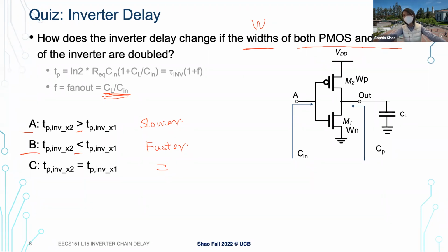But sometimes it actually makes sense to make more transistors or put more gates together that could potentially optimize the delay. But then we step out even more: at a high level, delay and throughput are two different optimization metrics, right? So we talk about the 1 gigahertz race, right? Back then it's how we get to as high a frequency as possible, as low a delay as possible.